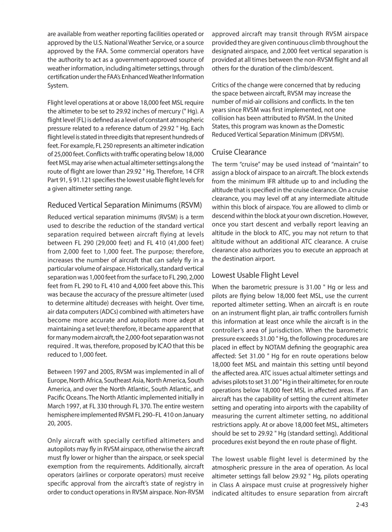Additionally, aircraft operators, airlines or corporate operators, must receive specific approval from the aircraft's state of registry in order to conduct operations in RVSM airspace. Non-RVSM approved aircraft may transit through RVSM airspace provided they are given continuous climb throughout the designated airspace, and 2,000 feet vertical separation is provided at all times between the non-RVSM flight and all others for the duration of the